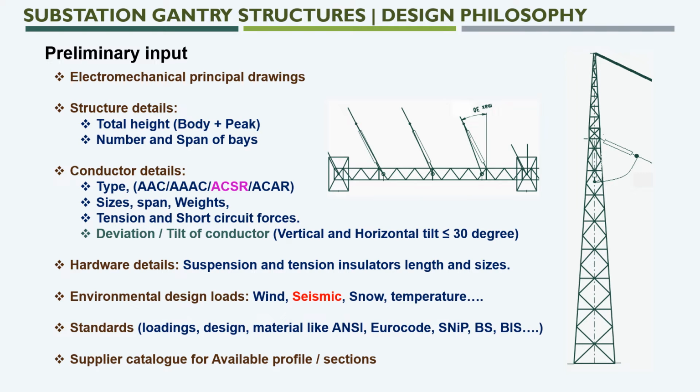This is another preliminary input. Here the standards mean which standards to be referred for loadings, design and materials, like ANSI, which is an American standard, Eurocode, SNiP which is a Russian standard, BS which is a British standard, IS which is an Indian standard, likewise Philippines, Indonesian, Argentina, Algeria. Whenever it is a seismic prone area or heavy wind area like Indonesia, Philippines and some peninsula projects, we need to calculate loadings based upon their domestic standards.